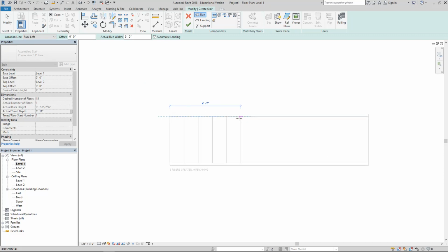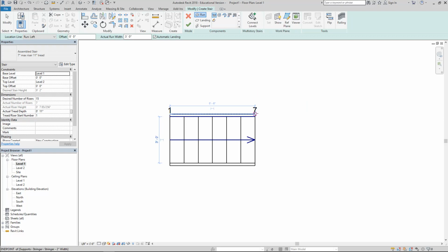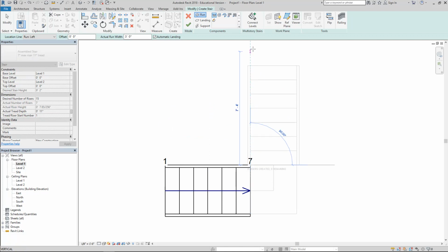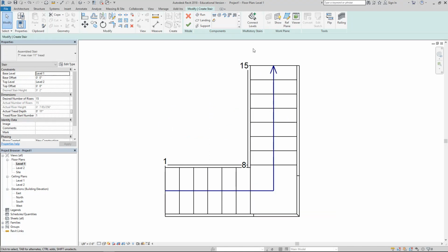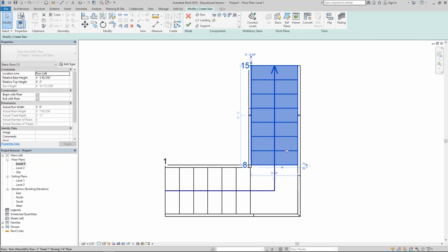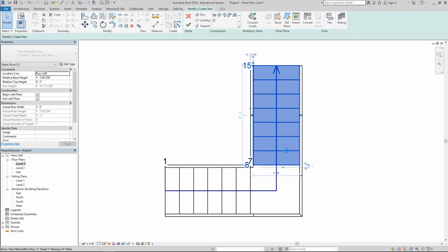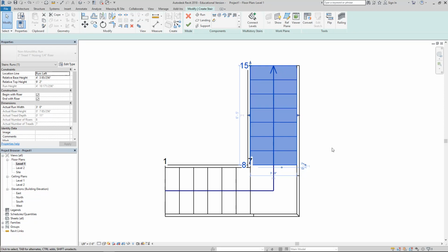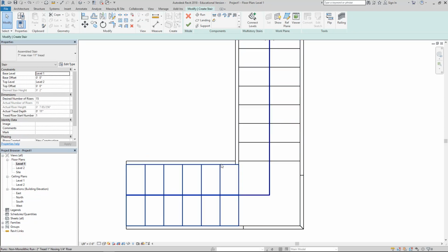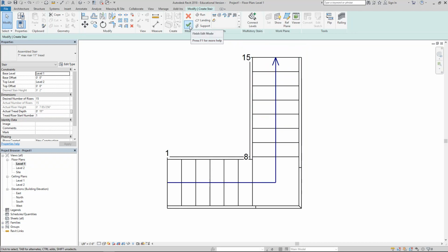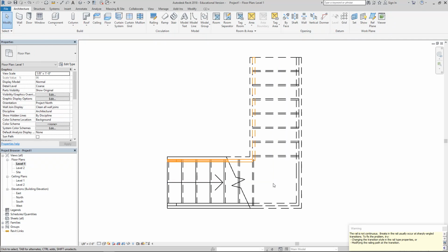So if I wanted to split this up somewhat equally, I'm going to click on 7 risers created, 8 remaining, and then I'm going to click there, and I'm going to do an L-shaped set of stairs, point in the direction that I want it to go, and then I'm just going to kind of bump this over until I get it to be exactly where I want it. I have that landing, the 2 intersecting risers there, and whenever I'm all done, I can click the check mark,